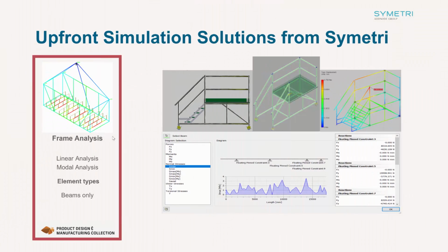Now, what we also have available is the frame analysis option. For those of you who work a lot with frame members, even within the Inventor application itself, you have the design accelerators for frame generation. What you can actually do is test out how your frames are going to behave in the real world environment by applying loads and looking at what the reaction forces are, what the displacement is going to be, and whether or not your frame members can be rated for the analysis you want to do.